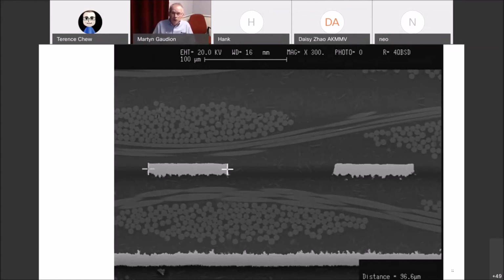So the loss from copper losses, the resistive losses, that's the power loss. It's turned into heat basically as current drives down the trace and returns through the plane. Then current traveling through there as the signal switches high and low turns into heat and gets lost, so it's no longer used to convey the signal. So that's where part of the losses occur. The other part comes from losses in the dielectric material itself.